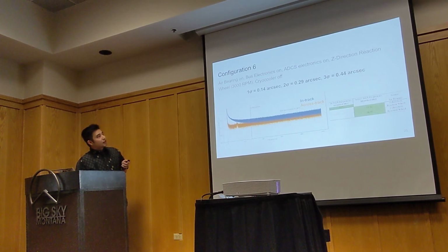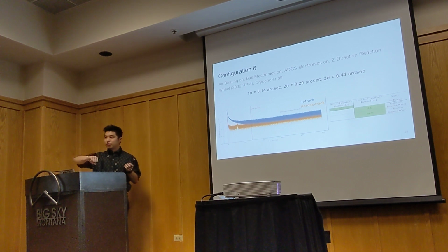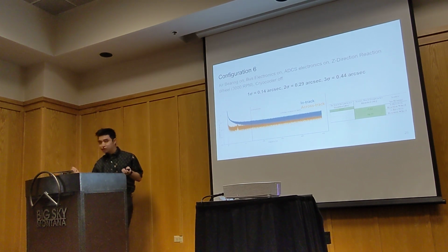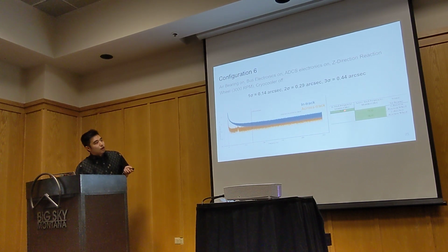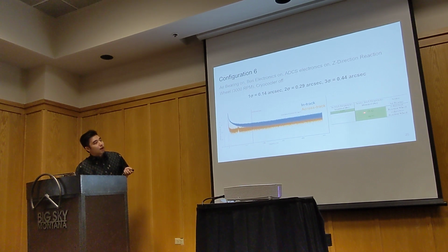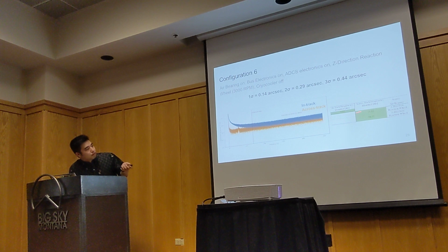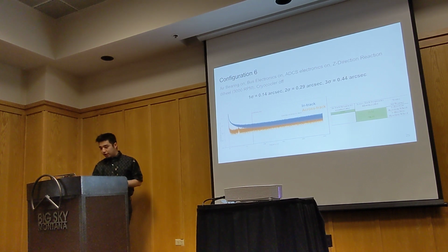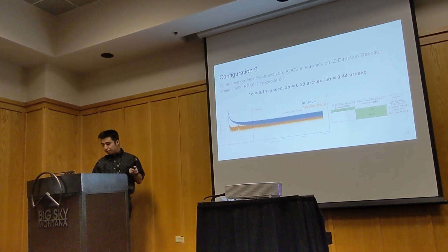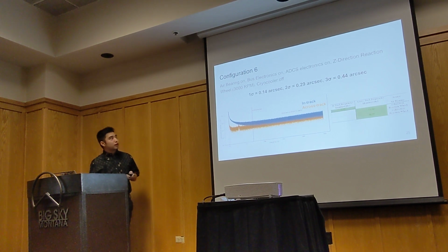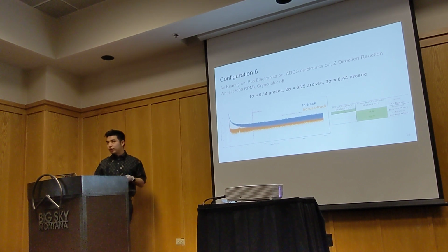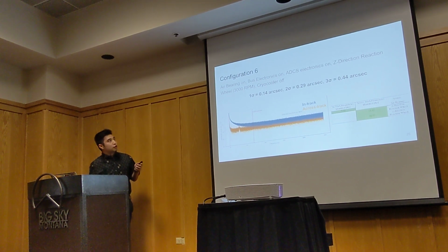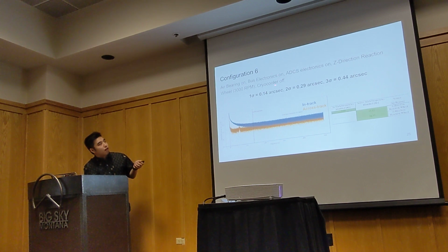Right, so the next configuration that we tested was we turned the X direction reaction wheel off, turned the Z direction reaction wheel on at 3,000, and now we actually see some new frequencies. So 0.03, this is air bearing drift, but in the across track direction, you see a subharmonic at 11 hertz and a peak at 58.27 hertz. Whether or not this is from the Z direction reaction wheel, we actually aren't sure. The only way to really confirm that is to look at the encoder data for the wheel, which we unfortunately didn't have for this trial. But you can actually see a very large drop in